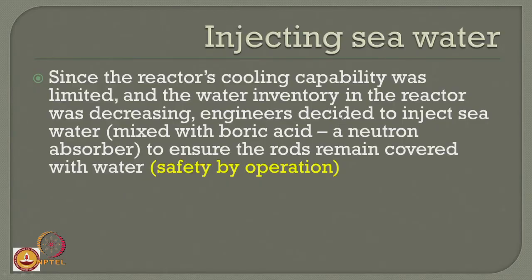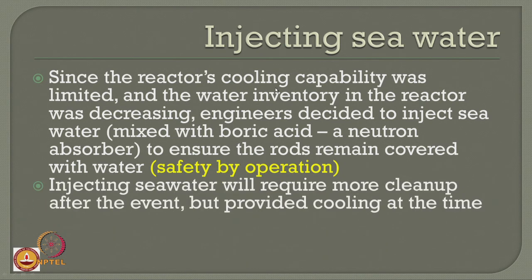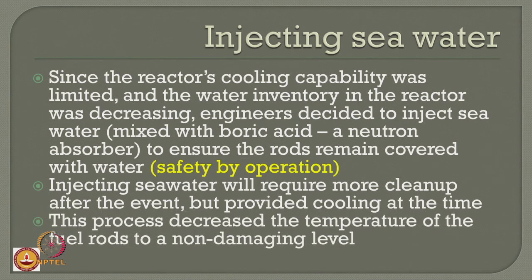Now, I would say this as safety by operation, because they did not pump the seawater directly, they mixed seawater with boric acid, which is a neutron absorber, and then pumped it in. But even then, injecting seawater will require more cleanup after the event, but it provided cooling at that time to control the heat in the reactor. Of course, fortunately and successfully, this process decreased the temperature of the fuel rod to a non-damaging level.